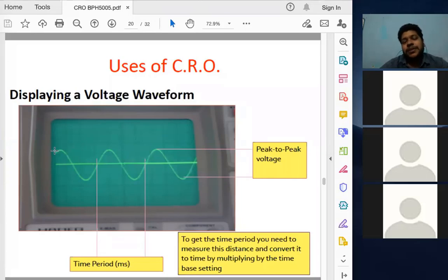So generally, when we trace, we need to have a scale associated. Then only from the trace can we tell about this. But since we need to have something in the card, we generally trace it to keep it in the card to just show its waveform. So sometimes we don't make a scale on the trace paper, but to make such measurements like voltage and frequency and all of that, we need to have a scale associated with that, so that we can claim this is this much distance. And then from the setting, we know the conversion factor, so that when we are doing peak to